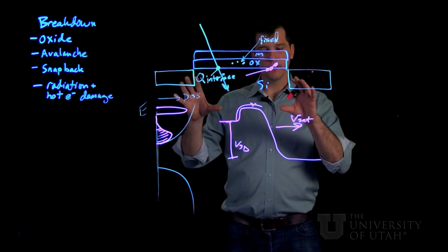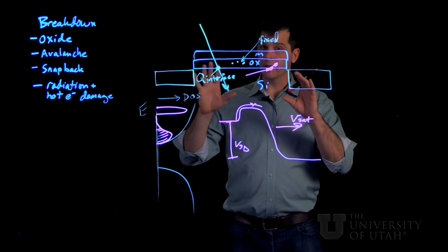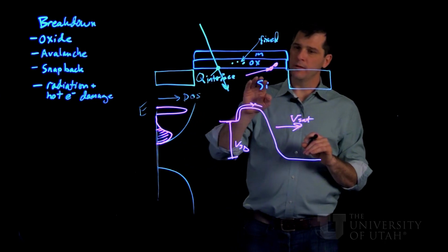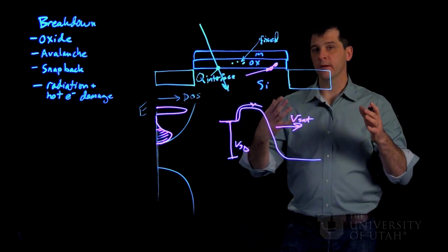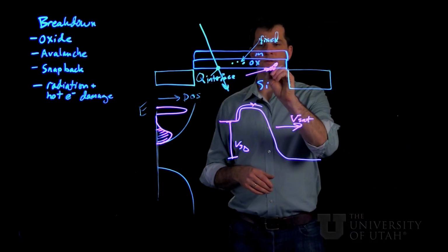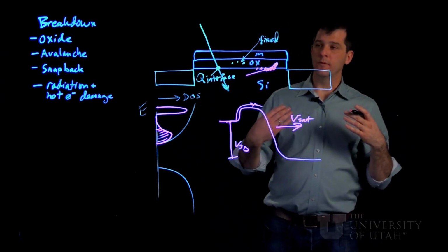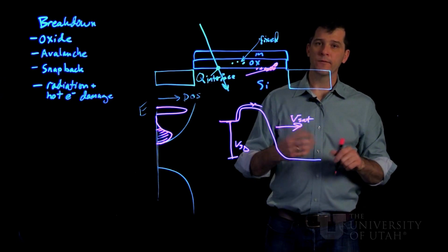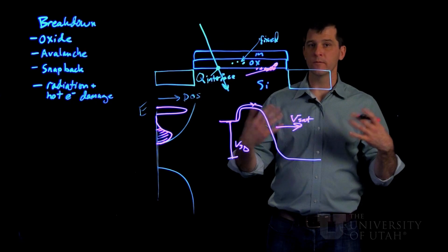The fact that the transistor itself is working at such high electric fields means that the very carriers that are making the device work can destroy it over time. So accumulation of these broken bonds would again change the threshold and other characteristics of the MOSFET itself, causing drift in performance versus time and eventual failure.